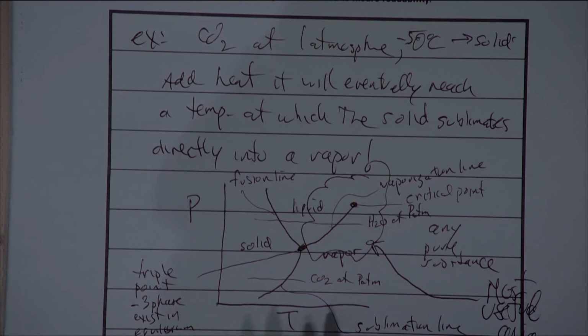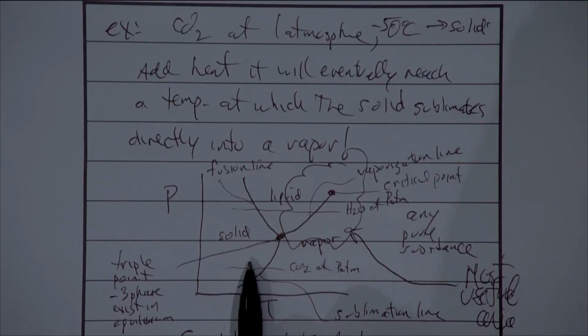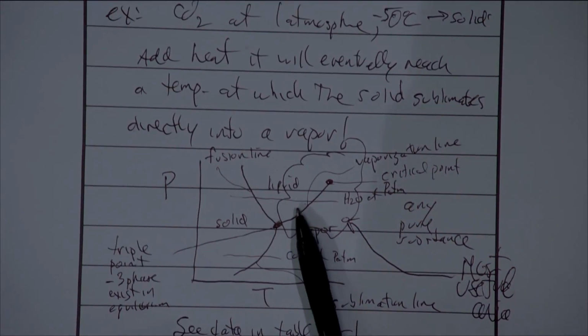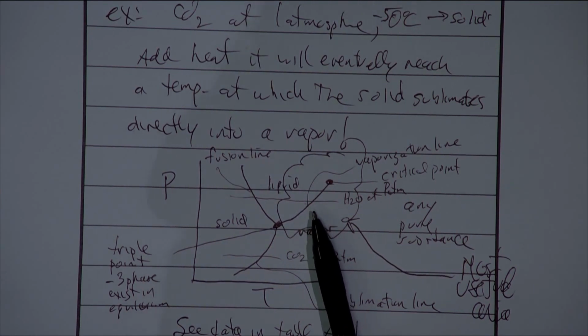Okay, it's most useful. So what I want to do is make a new drawing, a new set of drawings, which is going to actually be the drawing that we're going to use like 99% of the time as we illustrate processes. And that will be the temperature volume diagram. By the way, in case it isn't obvious, just because the pressure and temperature are in equilibrium doesn't mean that the other thermodynamic properties are going to remain the same as well. We know that when water boils from a liquid to a vapor, sure, the temperature and the pressure are steady, but the volume changes significantly, right? 1 pound of water is, what, about a pint, right?